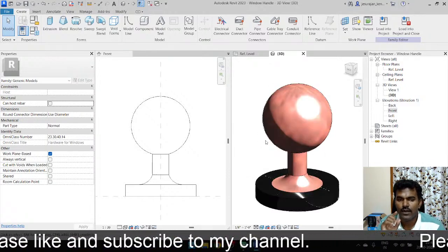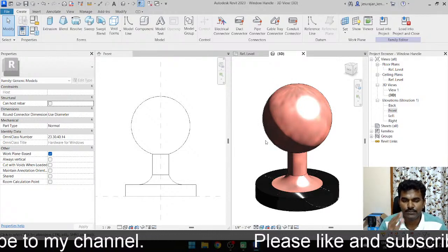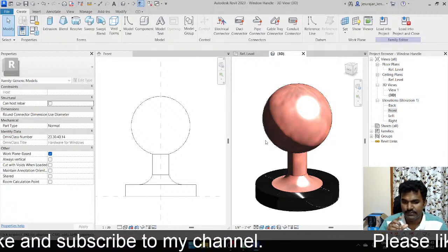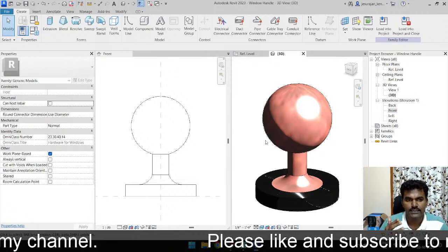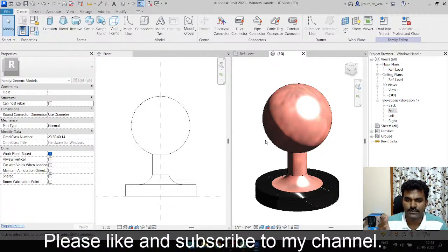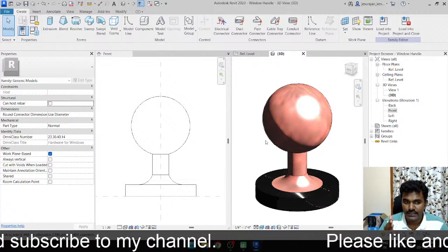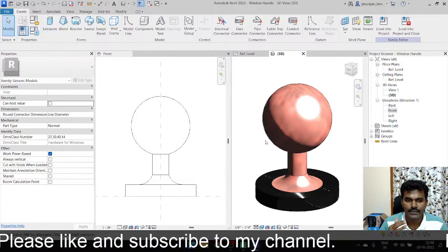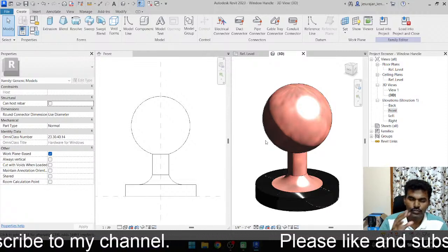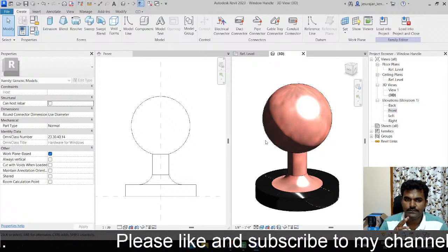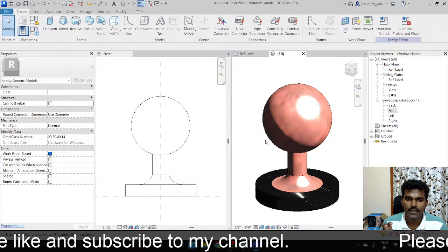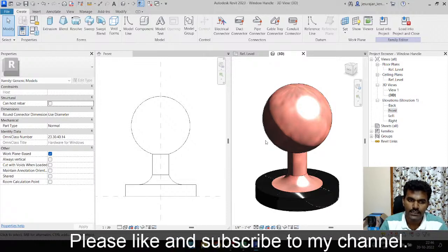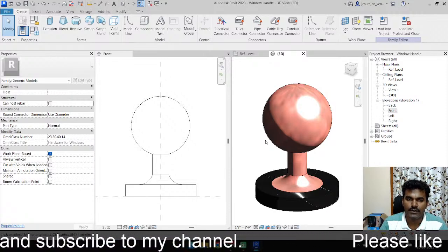Here what I'm teaching you is you don't have to make everything parametric. That's not required. When we are making a product with different sizes, then you can try to make it parametric. Otherwise you can just leave it. In case you're struggling to make it parametric, then you draw different families and create a parameter to select the family. You load 3 families and create a parameter to select a family, so that also will work.